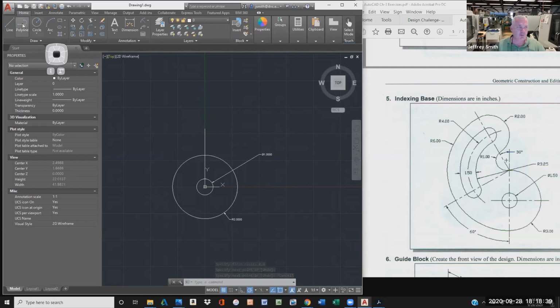And I'm just going to draw an arbitrary line. But what I want to do, I know that it's at 30 degrees. So I'll start here and I'll just go up. And then I'll hit the magic rotate, and I'll select this line. And I'm reading the command line in the bottom. So let me make sure you can see that. The command line says rotate select objects, push enter, enter. All right. The base point's at that intersection there, which is actually 0, comma, what's the radius? 3. Do it again.